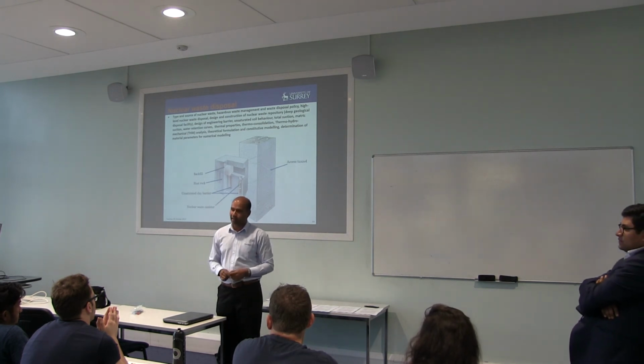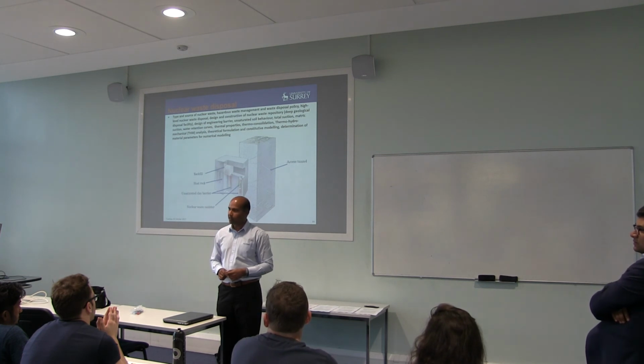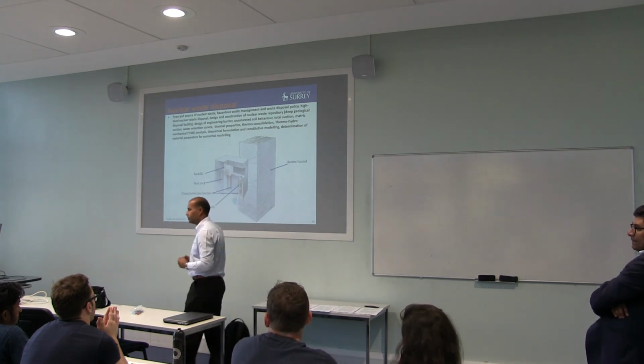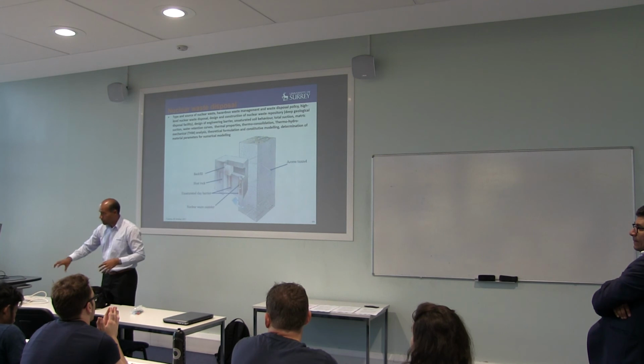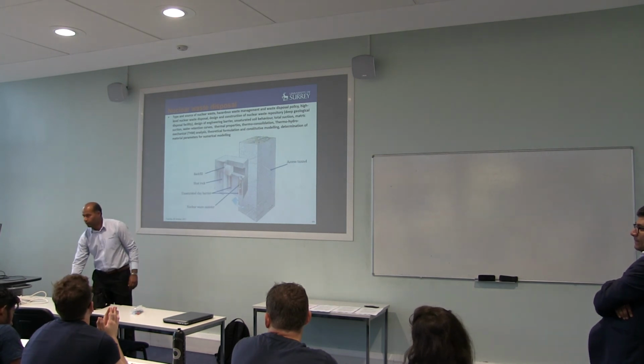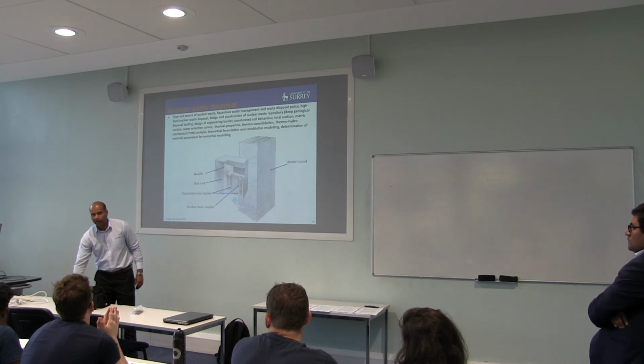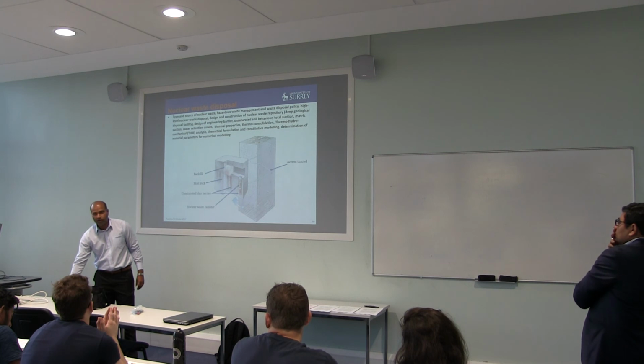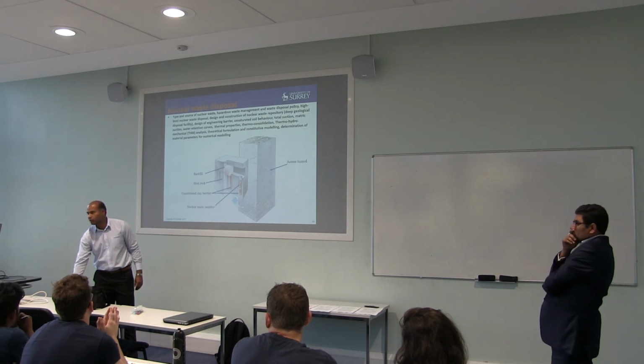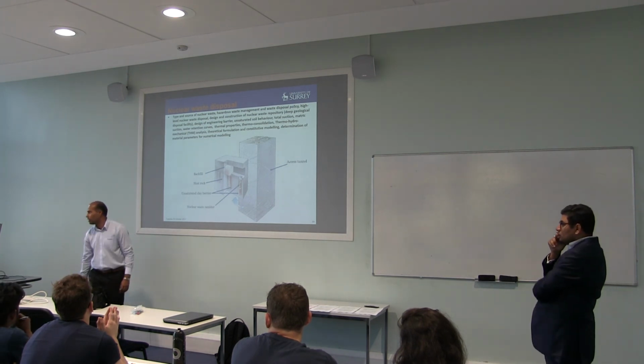But swelling clay is good in one sense: it's very impermeable. Let's say if I put water on this table, water can go through this table only if there are air voids. If there are no voids, it won't pass through. And that's what happens with swelling clay.